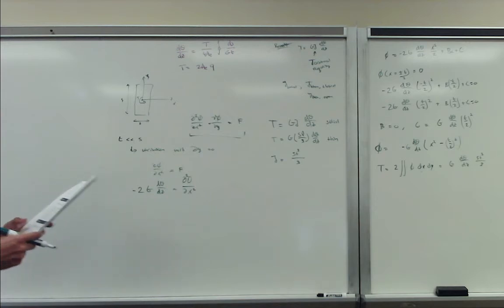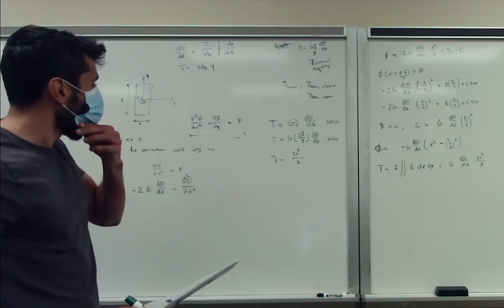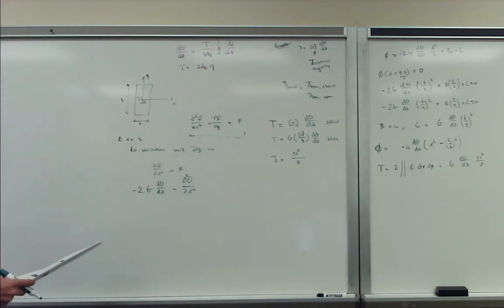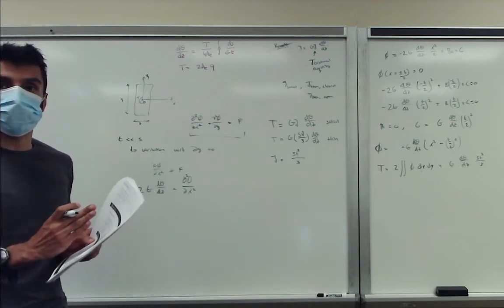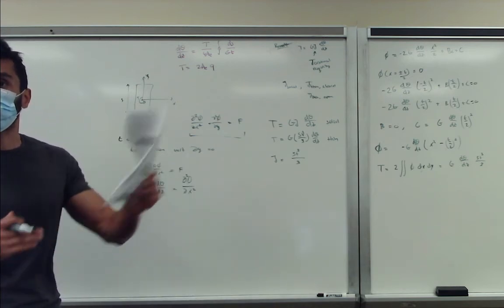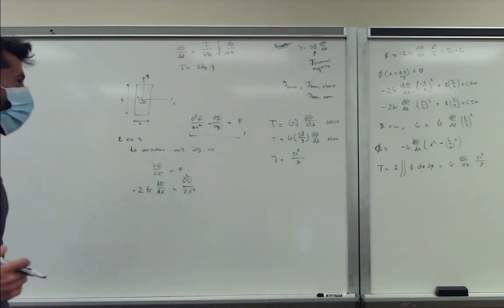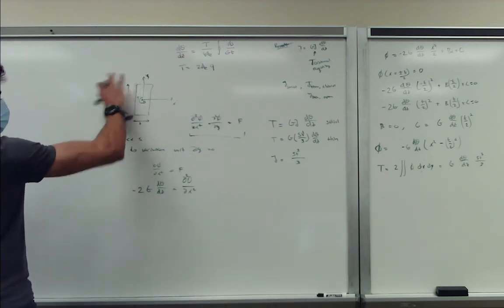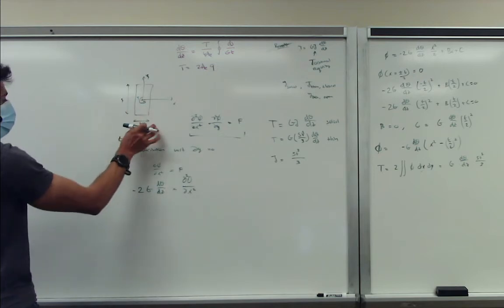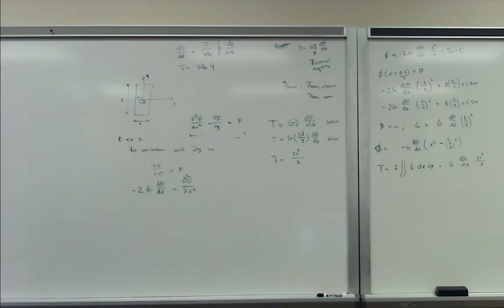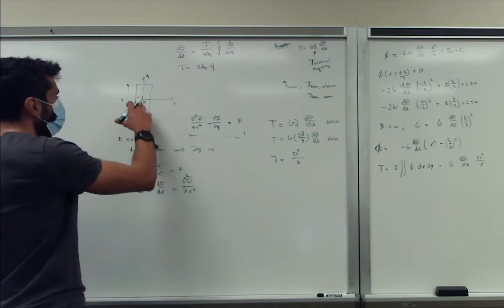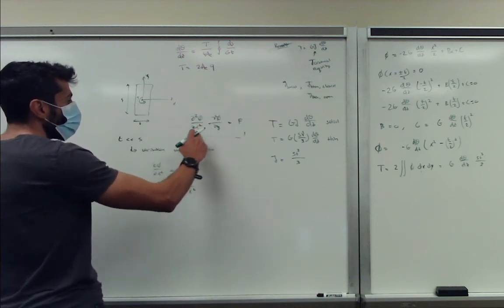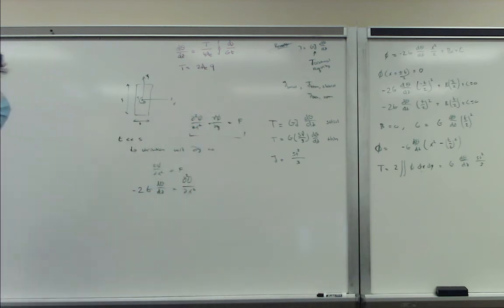So by comparison, in order to look at a thin wall section, we basically said, okay, let's look at our solid section. We squeeze one of the thicknesses to more or less 0, and we elongate the other length. In this case, we elongated the y distance and narrowed the x distance. Because of that, we don't get any variation for fixed x along y. So we could drop one of our terms in our governing equation for torsion of solids.